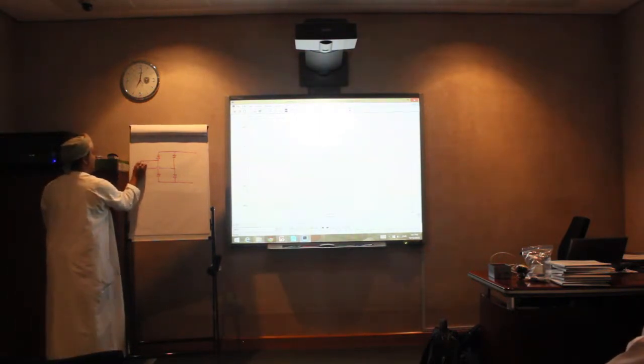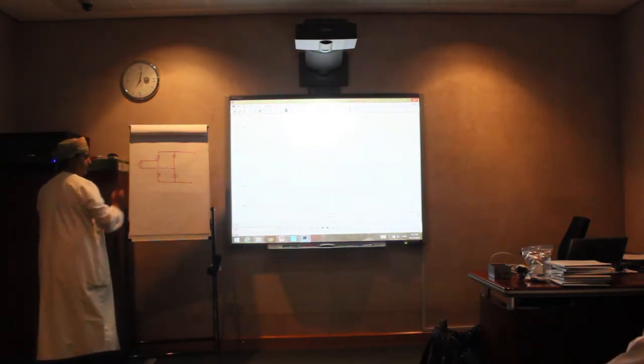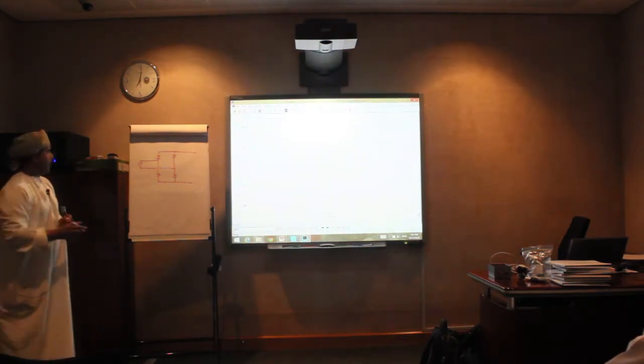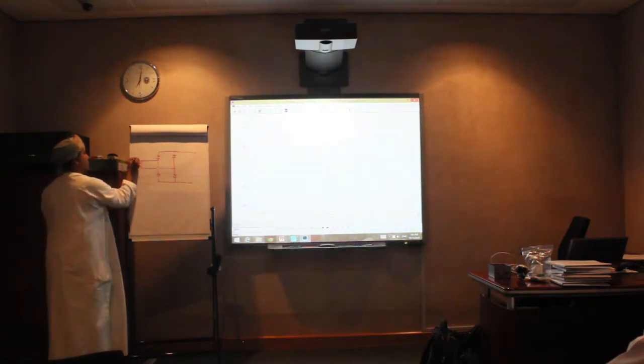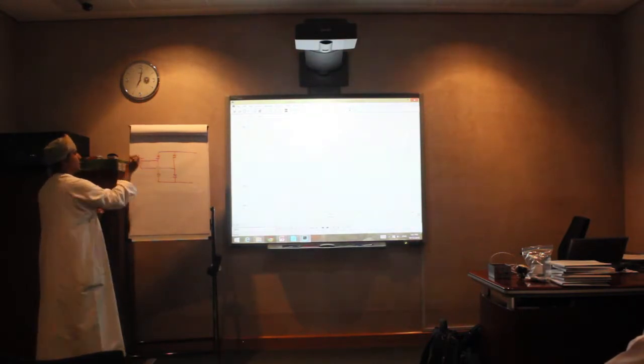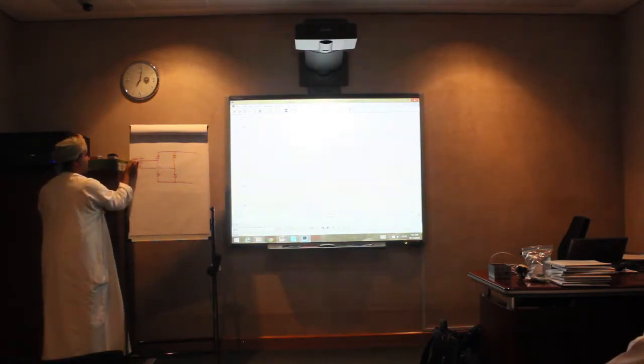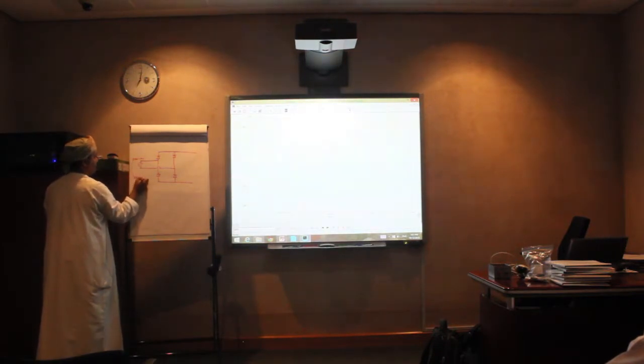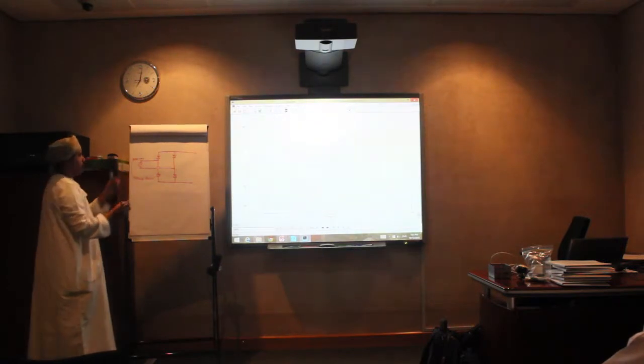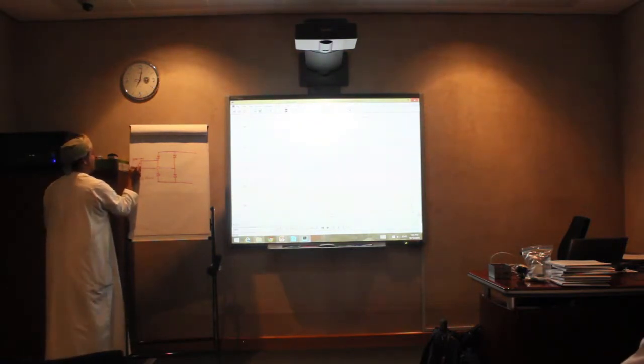So that means if I have an AC, the same thing like this, okay, and I can assume it now 240 RMS, which is like this system. So the peak of this one is 340 volts, because it's an RMS, right? And the frequency is 50 hertz, like our system.